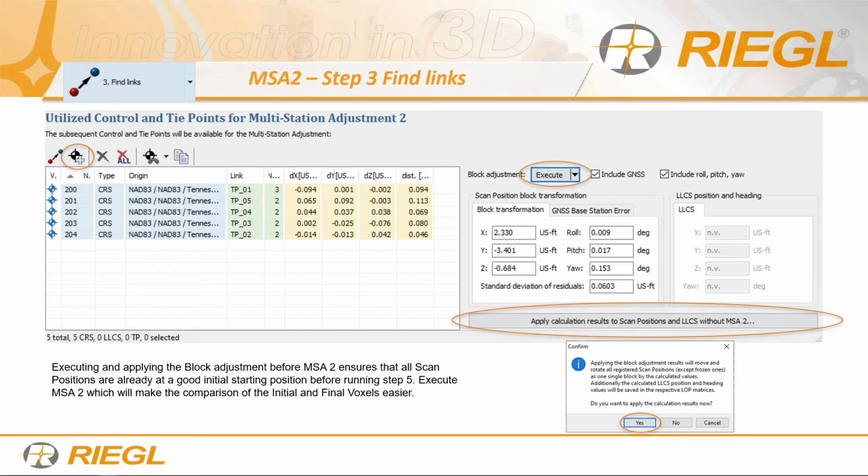Okay, so that's from the internal sensor. The block translation, which is the X, Y, and Z, is not far from where it started, so it didn't move that much. Well, it made sense because on this project I didn't use RTK, I just used the internal GPS, which is L1 signal. So the accuracy of my project was anywhere from 2 to 5 meters. So it wasn't a big transformation here. And then you want to go ahead and hit yes and just follow the workflow. Okay.